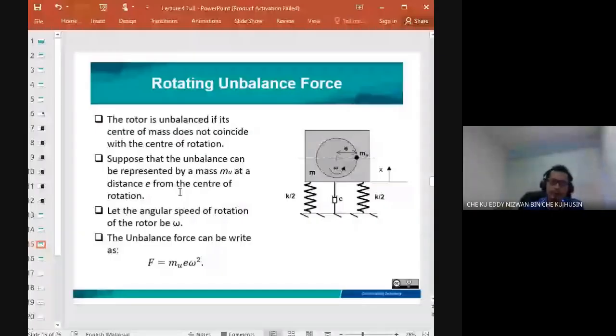So that's why in industry, if you face high vibration problems, you can refer to this solution. High vibration means high amplitude, and high amplitude is dependent on this. If there is a machine defect, it produces a higher force.